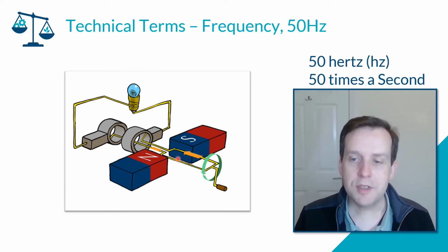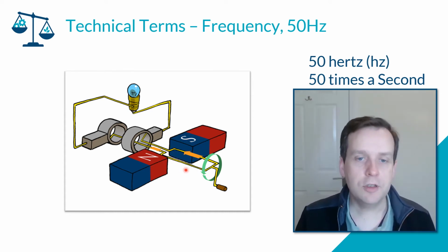So when you see a wind turbine rotating maybe once or twice a second, there's gears within the wind turbine, so the generator is actually turning at 50 times a second. Every single electrical generator, whether it's gas, nuclear, however, ultimately this rotation is 50 hertz or 50 times a second, and that's where we get what we call our frequency or system frequency.